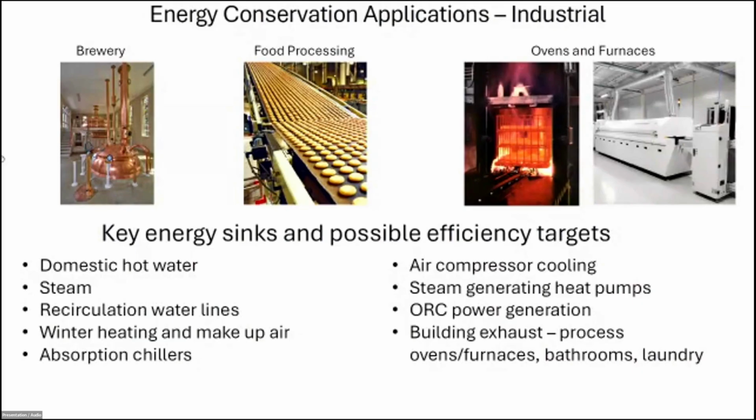So a good example, I was working with a food processor recently. They focus on extracting essential oils from different things. One of their processes was mint leaves. They extracted mint oil from mint leaves by injecting steam into the system. They're currently using a gas-fired boiler to provide that steam load, that low-pressure steam load, to extract that mint oil, and they're under electrification initiatives. So they're looking for ways that they can electrify that load. So I'm helping them look at a waste heat recovery system to capture waste energy from another part of their processes, bring it into a steam generating water source heat pump to electrify that steam load for them.